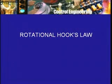And now something like the rotational version of Hooke's law will tell you that the twist is proportional to the torque. Just as for the spring, the force was proportional to the extension, there is a rotational Hooke's law which can be used, and therefore the torque generated by the motor can actually be measured. Of course, what is really measured is the torque transmitted at any one particular cross section of the shaft.